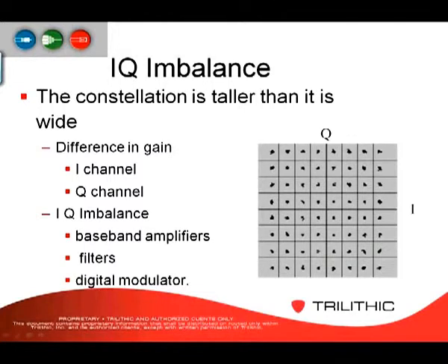Then there's IQ imbalance. With IQ imbalance, the display will look taller than it is wide. This is going to be a head-end type of issue that comes from baseband amplifiers, filters in the head-end, digital modulators, and so on.